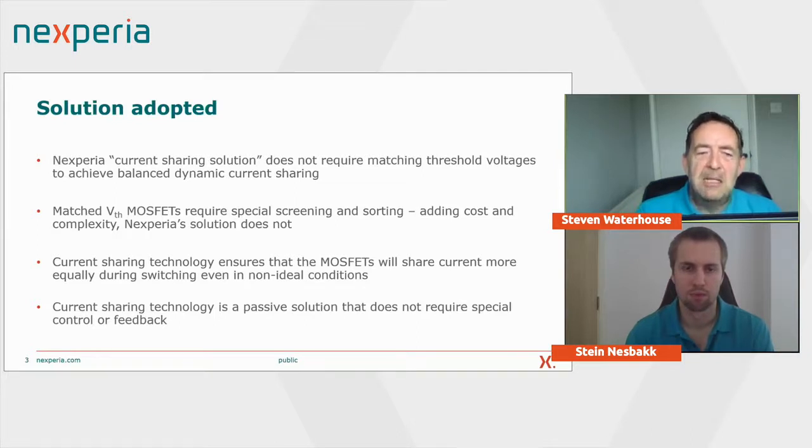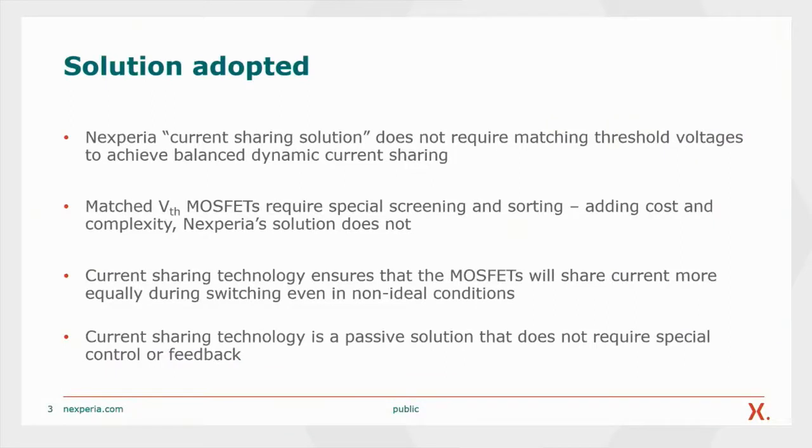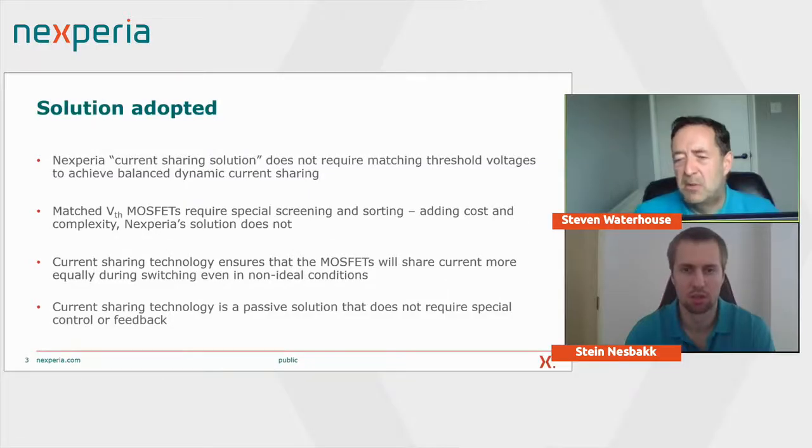We design this capability. The current sharing technology ensures MOSFETs will share current more equally during switching, even in non-ideal conditions, during the turn on and turn off of the MOSFET. And it's a passive solution. We don't require any special drivers or any control or feedback. The MOSFETs will share current based on the technology that we've designed. I'm now going to hand over to Stein, who's going to go into a little bit more detail about what we've done and some of the testing we've done.